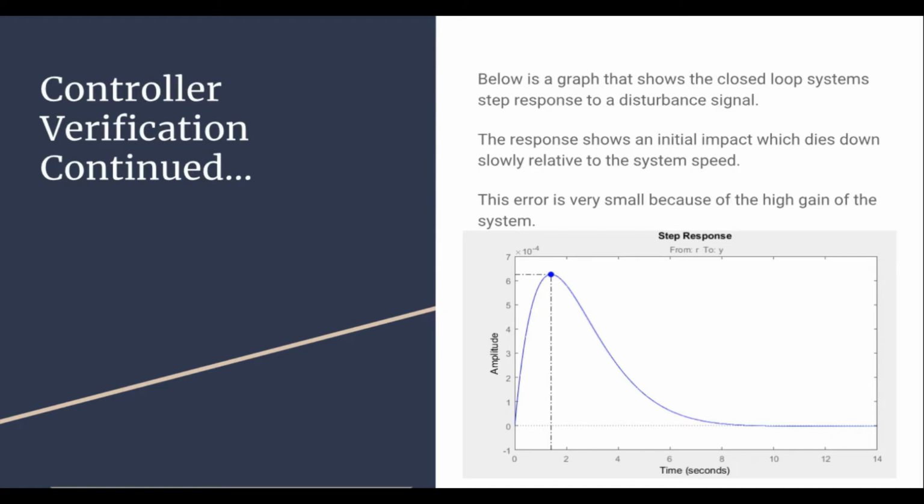This is because our feedback system has the controller in the feedback loop for a disturbance, and the gain on our controller is very high, meaning that its effect on the output will be very small. Disturbances that our system could see would be things like gravity, wind, or potholes. These things would act as step disturbances because they would be static as they are happening.